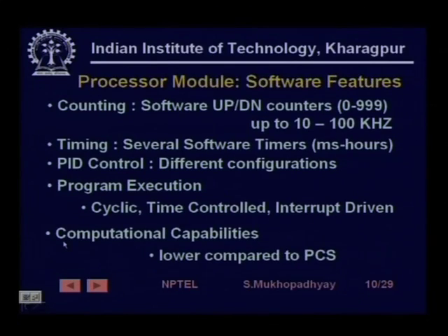But all said and done, one must understand that typically a PLC has much less computational capability compared to a PC, although it is generally much more expensive. That is, if you take PLCs and PCs of the same kind of price, then you would find that the PLC is much less computationally capable compared to a normal PC which sells in the market, both in terms of memory and in terms of computing speeds. That is because price of things get actually decided by the sales volume, plus the PLC has certain other features, they are actually very rugged and they have a different kind of packaging. So, all these things make this so, and the third reason is that a PLC is not a general purpose computer.